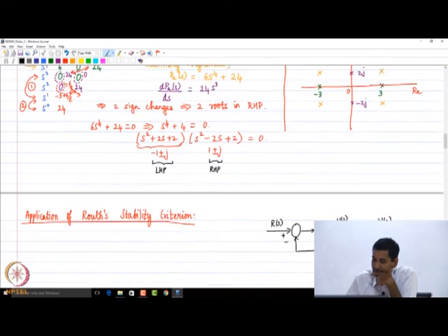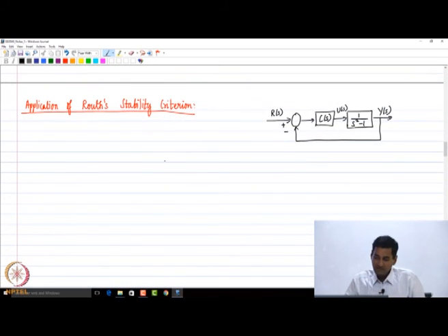Fine. Okay. So I think what I'm going to leave you with as homework is to look at this plant. The plant transfer function is 1 divided by s squared minus 1. Obviously, it's an unstable plant or system, right? Because you have roots at +1 and -1. Try to stabilize it using P, PI, PD, PID, whichever controller works, figure things out, right?